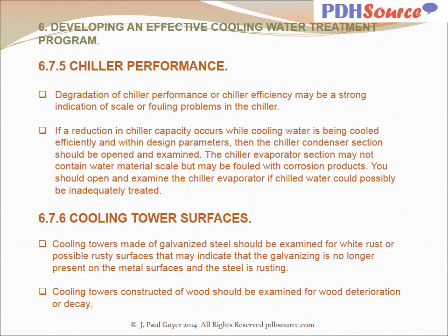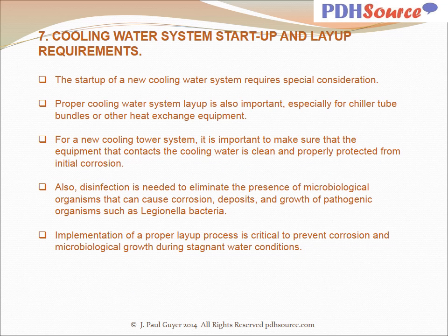Cooling towers made of galvanized steel should be examined for white rust or possible rusty surfaces that may indicate that the galvanizing is no longer present on the metal surfaces and the steel is rusting. Cooling towers constructed of wood should be examined for wood deterioration or decay.